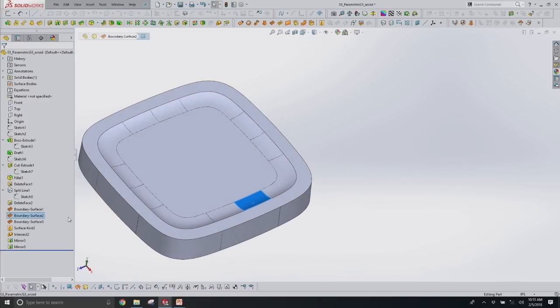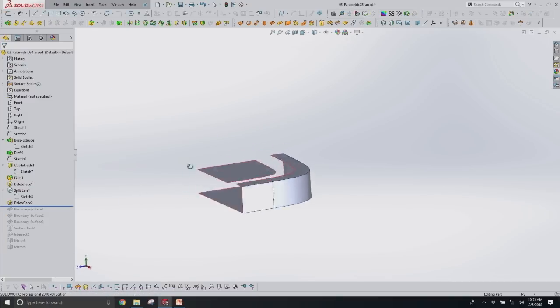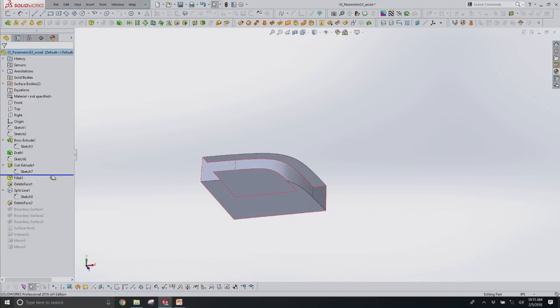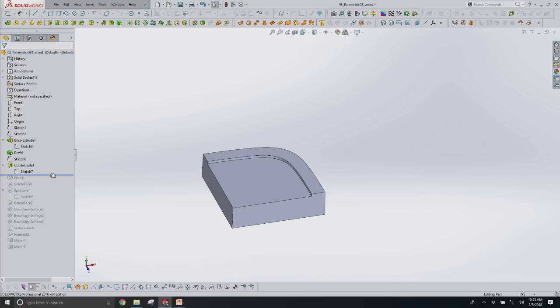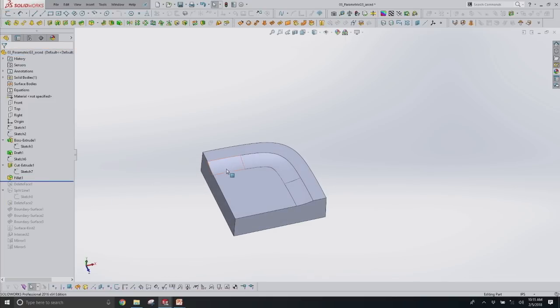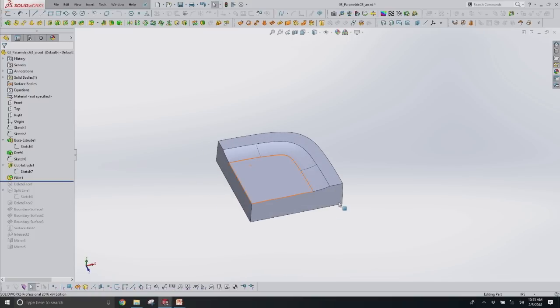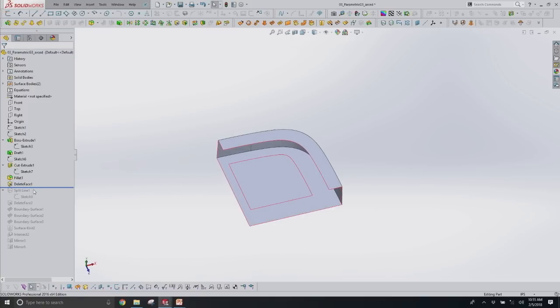So actually, real quick, we're ahead of schedule, so why don't we take a look how we made this. So here I used the fillet tool to just define a set of edges. This was just a quick way of me getting this edge. I want to make this kind of scalloped shape on the top of this whatever Wi-Fi router, IoT home device. So I'm using delete face tool to delete those faces I didn't want in the model.